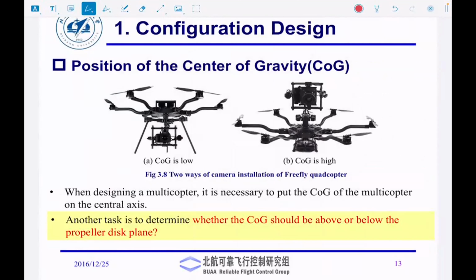Now, next thing is, the center of gravity of the aircraft is super important, because depending upon where the center of gravity is, the aircraft would be stable or unstable. I give you a very simple example. If you are walking, you would fall down if your center of gravity is outside the span of your legs. In other words, if CG goes outside a certain range where the internal moment, rather than stabilizing, destabilizes, the thing falls down. And that's exactly what happens in the case of aircraft. That's exactly what happens in the case of quadcopters.